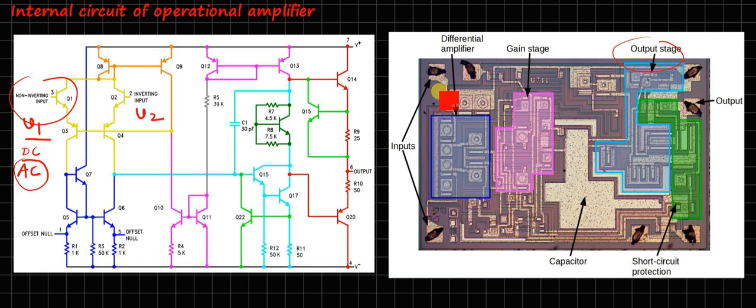The circuit can be designed and manufactured using MOSFETs also. The circuit using MOSFETs has different parameters and higher performance as compared to BJT. This is the BJT version; specifically 741 is made using BJTs. This is the older version of the circuit, and it has offset null pins available in the IC.